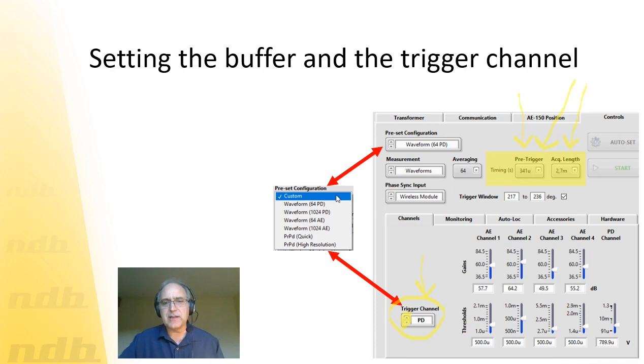So it means a little amount of time will be before your trigger, and the majority of your buffer will be after, in order to see the acoustic coming.